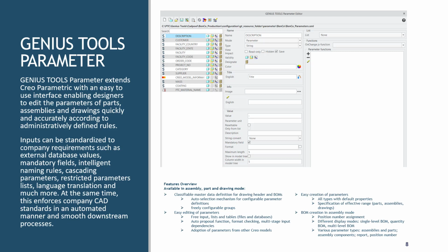Just about every company that we walk into, one of the biggest challenges they face is getting correct attribute or parameter data applied to Creo objects and in turn pushed to Windchill. Parameter values are either incomplete, not uniform, and because of Creo and Windchill functionality, some values are applied in Creo and others in Windchill. For example, cascading attributes were a big enhancement in 11.1, but are non-existent in Creo.